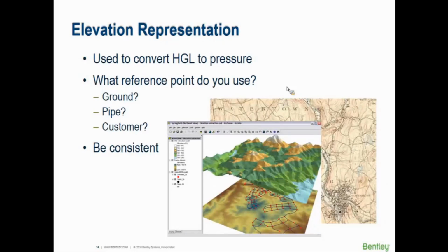If you're going to test the pressure on that pipe, where do you test the pressure? Under most circumstances, we're never actually down at the pipe level. We're a couple feet above. And that couple feet above is actually a pressure change because we're going higher, right? But generally, you're testing pressure at a hydrant. So that's the relative elevation point that you would be comparing to.